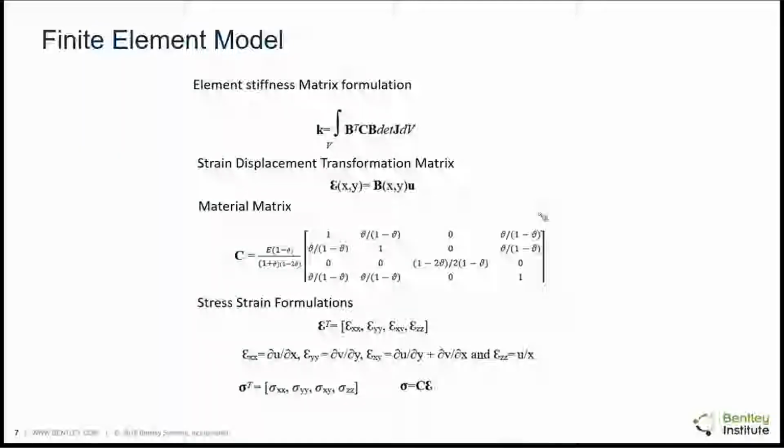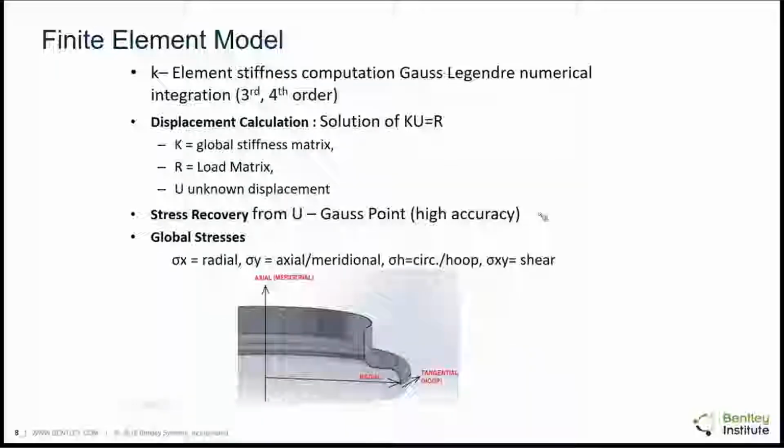You do not need to use 3D elements because it would be computationally much more expensive to use a 3D element for the solution. And here there is no torsion or bending, so it is assumed that the system is stiff enough against bending or torsion because of the tube bundles. So the axisymmetric element works perfectly fine, and that is what has been proposed in TEMA 9th.